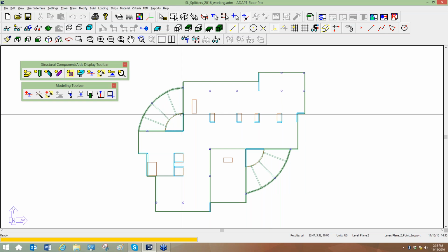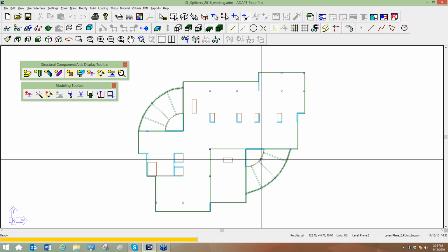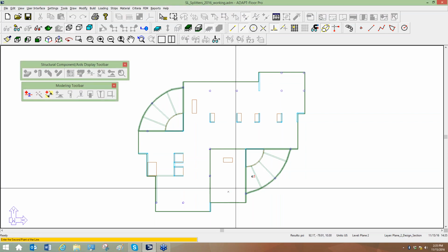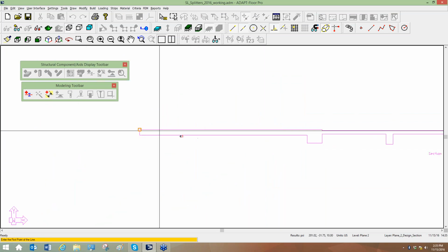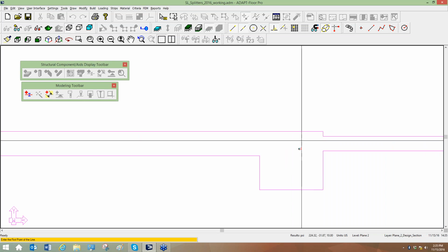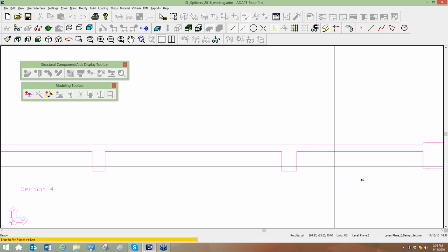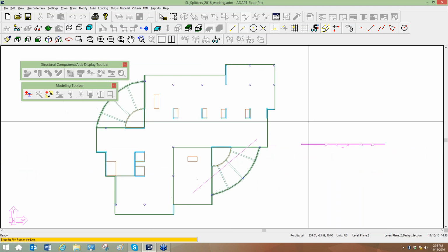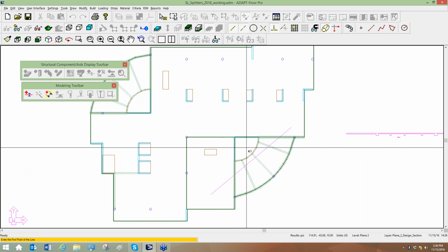And then we have these two areas out here that are essentially sunken. They're dropped, I think, 2 inches. So if I take a section cut from here over to there, let's say, you can see this is my 10-inch slab. There's a step right there at the face of that beam, and then I get into that one-way slab with beam, kind of the arc region, and then I get back over into another 8-inch or 10-inch slab. So, and in between there's an opening there and there.